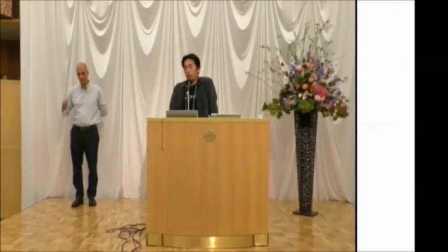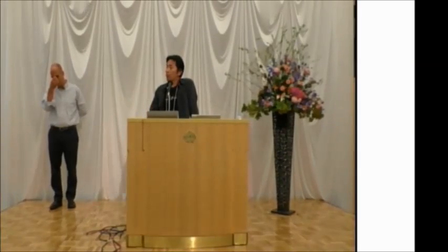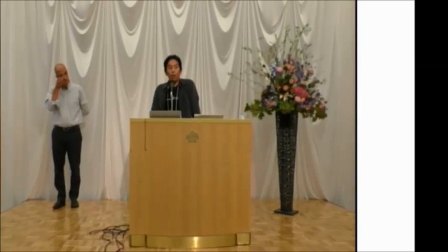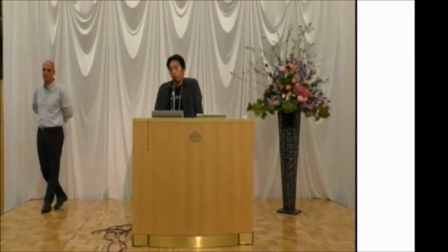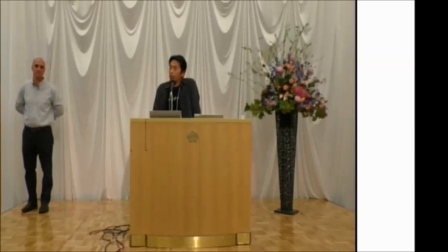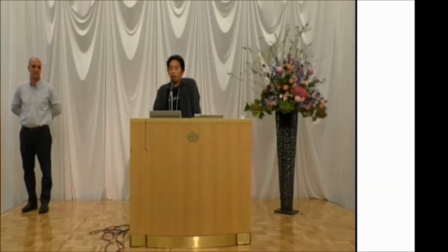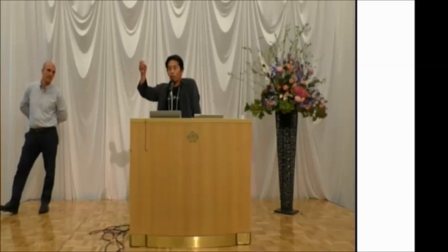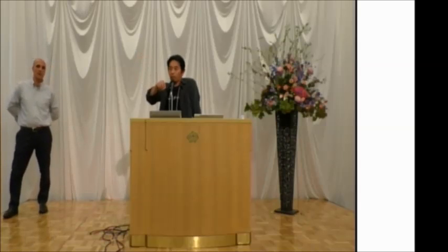So bank erosion must be a very important factor to calculate the bed deformation process, or also the channel deformation process. In this calculation, we are using a very simple model. We are considering the angle of repose, and the sediment will slide from the top of the bank to the bottom.